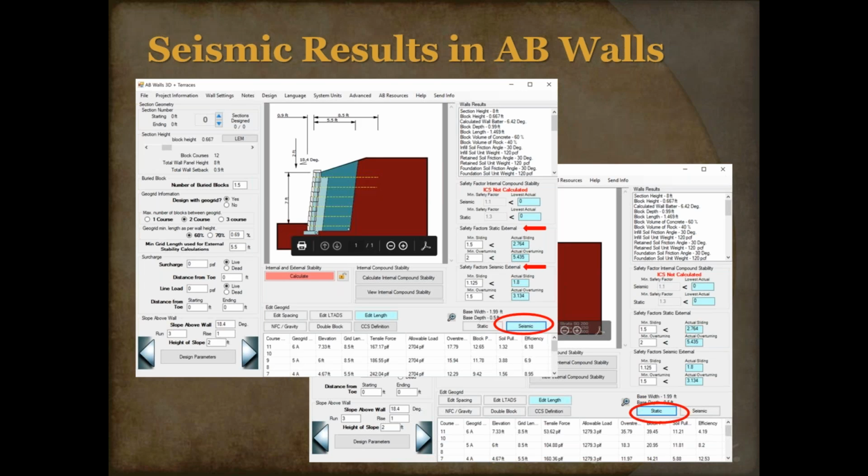One would argue that if I can go 3 inches on a 3-foot high wall, can I get a little bit more? Well, at some point, if you get more than 3 inches of deflection, you're going to get some major movement and probably result in problems above that wall. So we always use that 3 inches of deflection as that control. Great question, I appreciate that. Very insightful on that one.